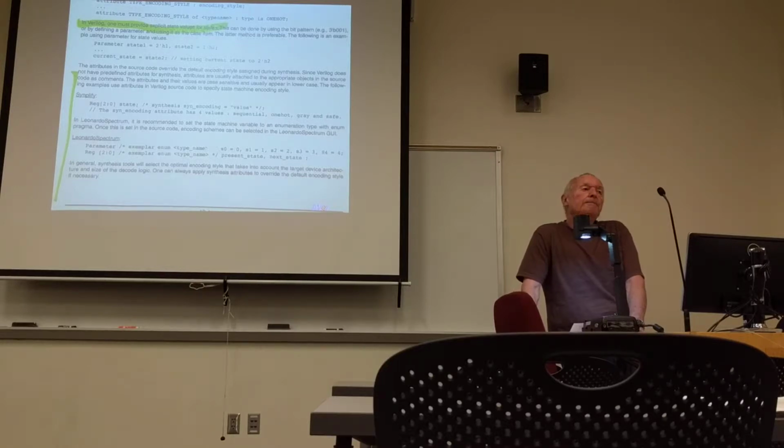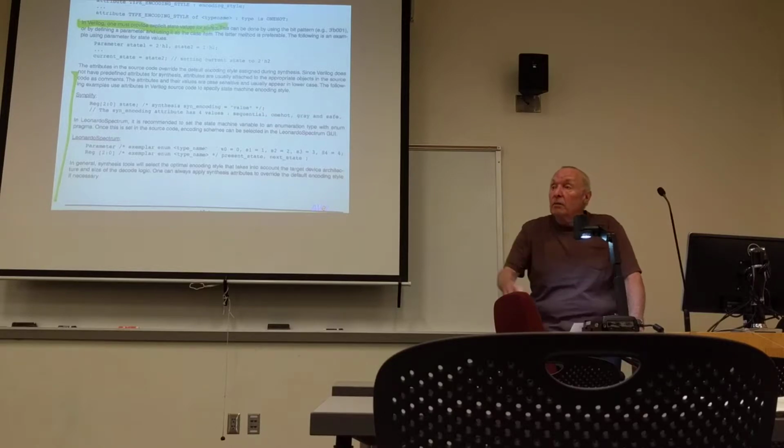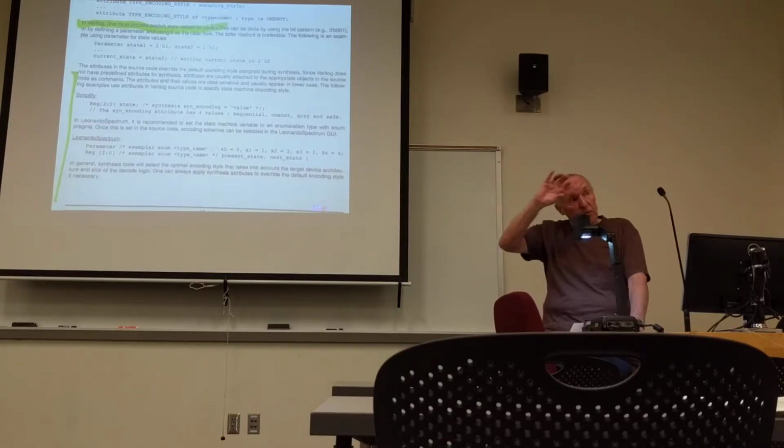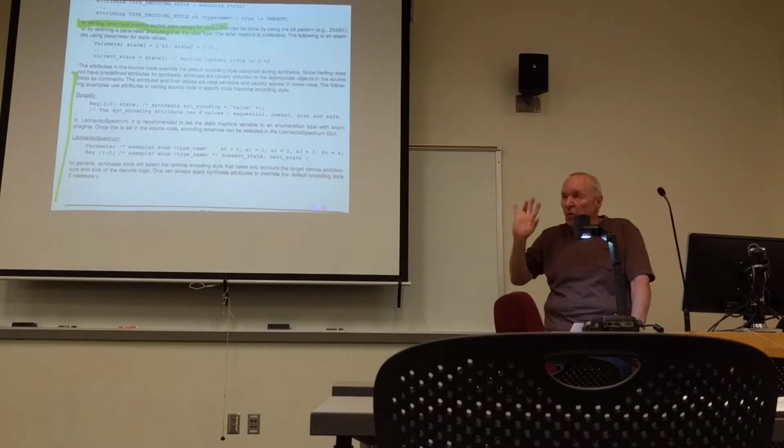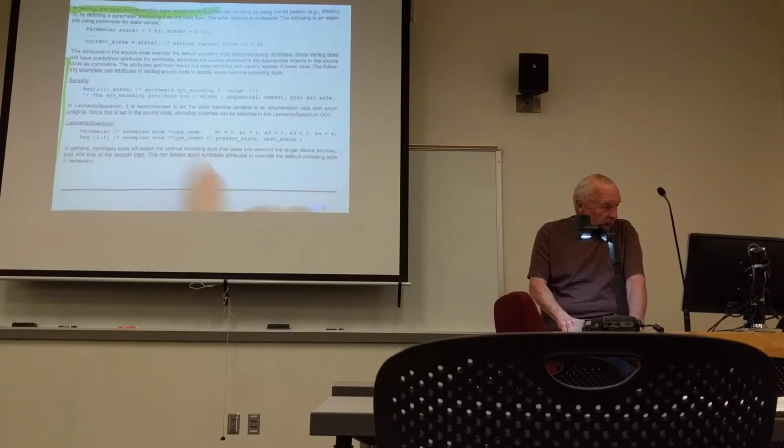One is you'll find that it is a synthesizer option. When you set up your synthesizer to synthesize a design, you come to a phase where you say, I want my finite state machines encoded with one-hot encoding or binary encoding or whatever. Another way you could do it is in your Verilog code.